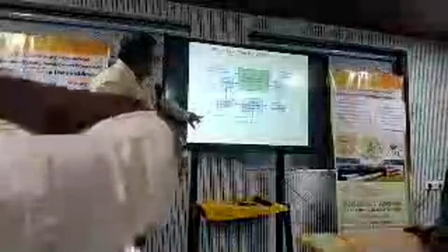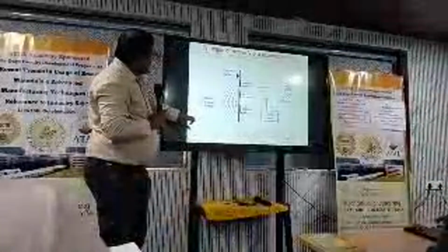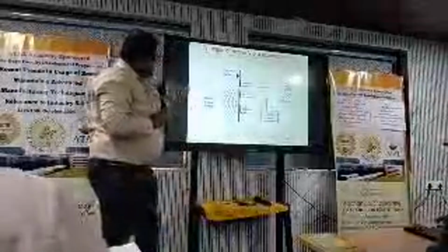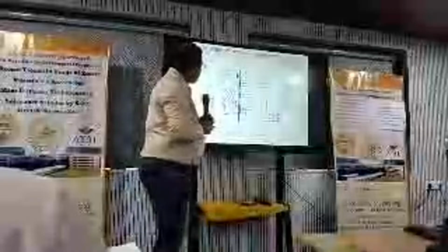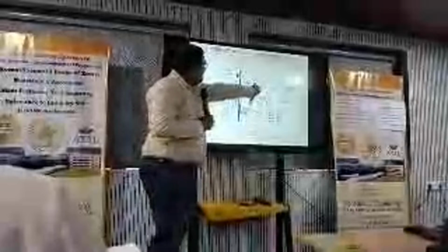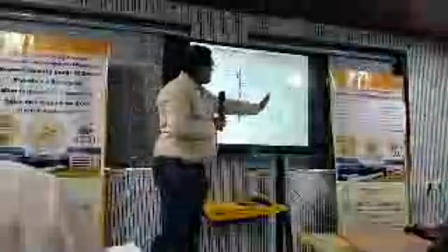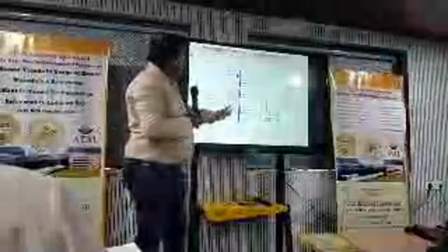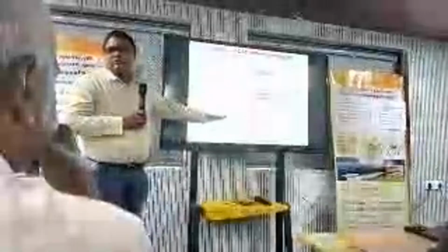There are different types of active vibration control. Another example is the same. An acoustic wave is coming in this direction, but I want this plate to be in a stationary condition. Then the sensor will measure, and the actuator will give energy in the opposite direction. This is the primary source, this is the secondary. Finally, it will be in a stable condition. So you have the primary wave in this form, and you supply the secondary wave in the opposite direction. Finally, my residual signal is zero. This is the active control phenomenon.